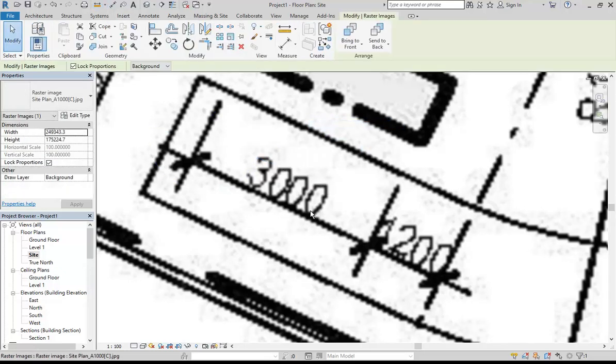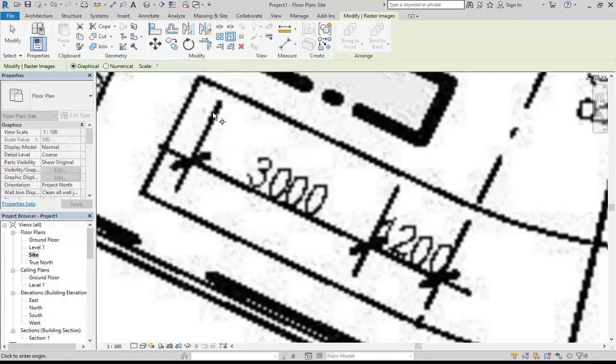All right, so now I'll do the scaling properly. So again, I've selected the image, and I'll click on the scale button. And so always with digitally produced CAD drawings, you measure to the centre of the line. With hand drawing, it can be different, but definitely with computer drawings, always to the centre. So here, I'm going to go from the centre of this dimension line to the centre of the opposite one, really trying to keep it at that angle.